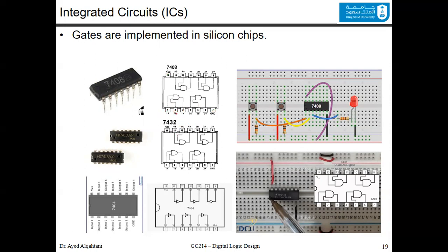To see this connection for the 7408, this is a model. You will say that, okay, this is 7408. And you will connect this, the purple line, to a VDD source. So the VDD source should be connected here. This is the VDD, and it's connected to all these dots. So you notice that we have a VDD and we connect it here. And here we also have a ground in the above pins. And we connect the ground to this pin, which is this pin.